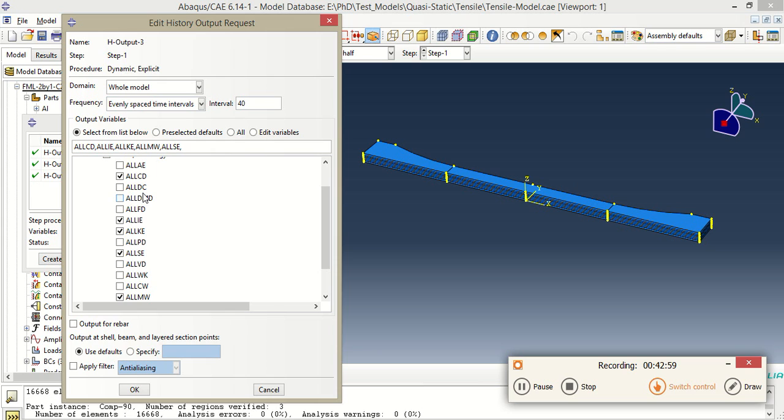We used the damping parameters in the case of composites. When we were modeling it in the material model, we chose 0.00007 and 0.01, I guess. So due to inclusion of that damping, what is the change in energy? So ALLCD will give you that, and that effect is very important. So see that these things should be very small with respect to the internal energy of the system.